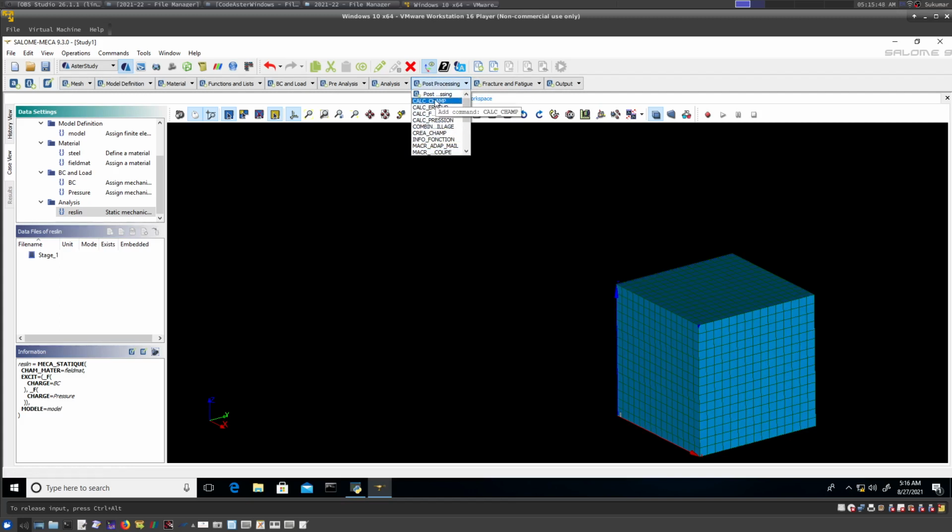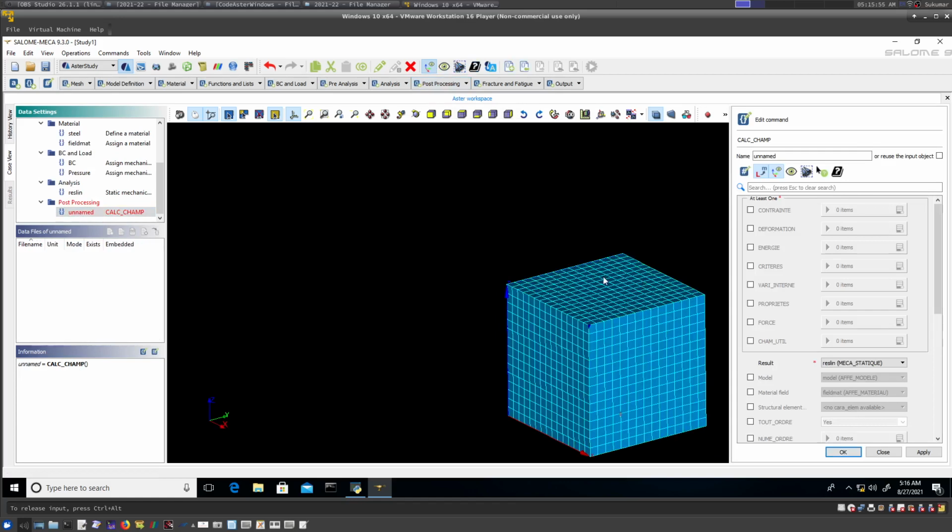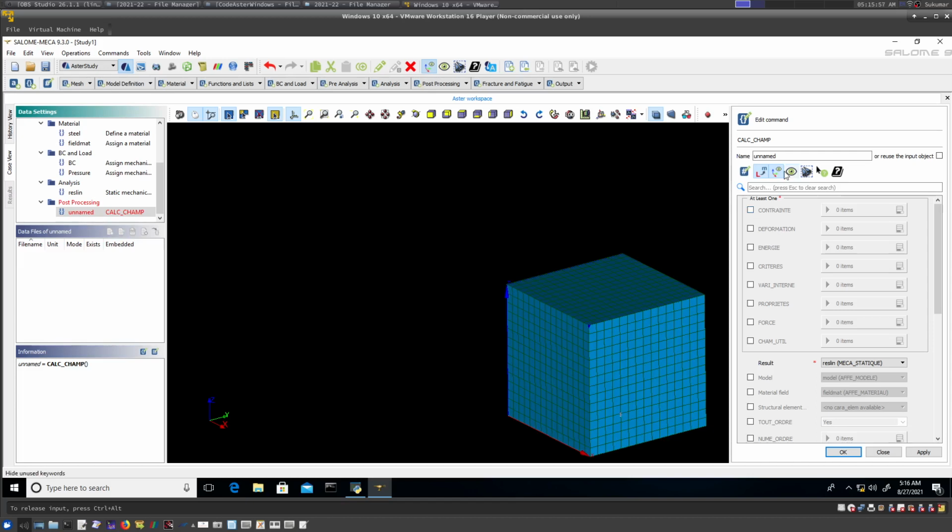We use CALC_CHAMP, that means calculate the field. CHAMP means field. I must use the same name as the analysis name.